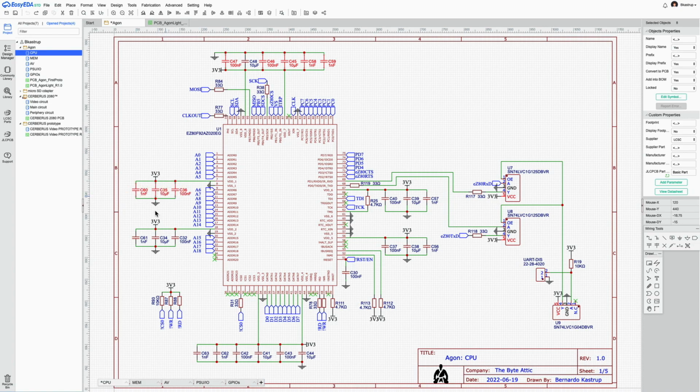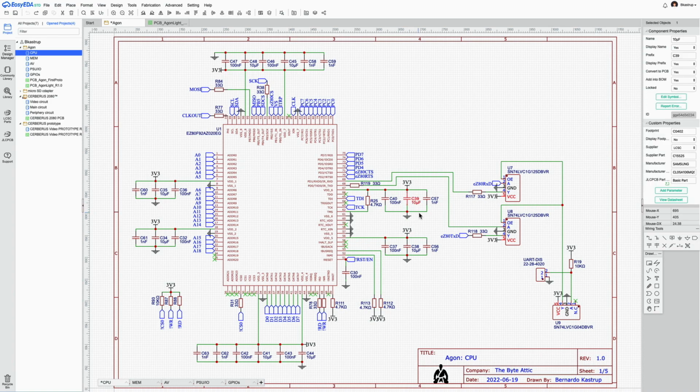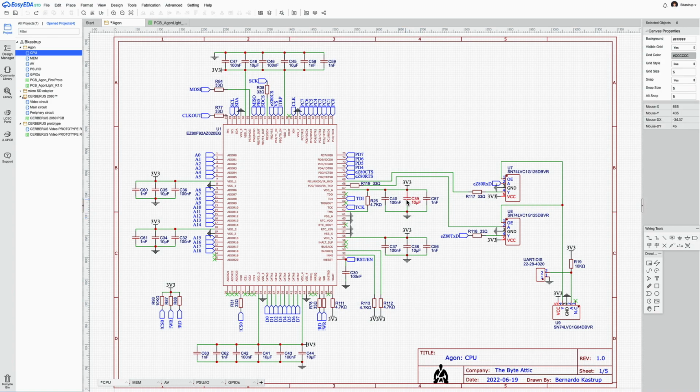Here you have them as well. Here on the other side, over there, there, and there, and so here below. They are everywhere. So why so many bypass capacitors? Well, modern wisdom is that only one would do, perhaps the 10 microfarad capacitor, because these SMD capacitors are so small, they hardly have any leads. And without leads, they don't have any inductive reactance.